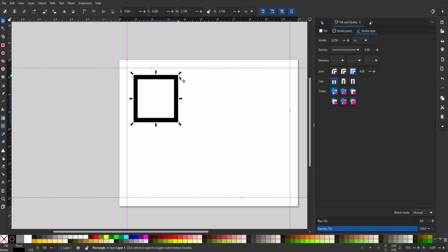If I have this object, there are a couple of things I could do. I could etch this into the surface, or I could create 2 cut lines from this and cut those lines. So to etch it, we can leave it as is, because etch is going to read it like a raster, and you don't have to worry about that. It will read black and white, and it will etch what is black.